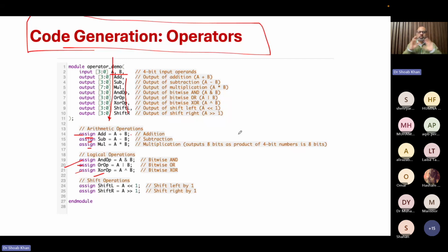These statements don't happen in any order of priority. This is something you need to remember in Verilog, because it is hardware. The simulator may execute this first, and then this, then this, or in any order it may want to. So if all the assignments are on different variables, then you don't care, because they are all on the left hand side.